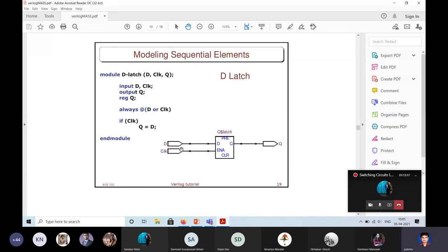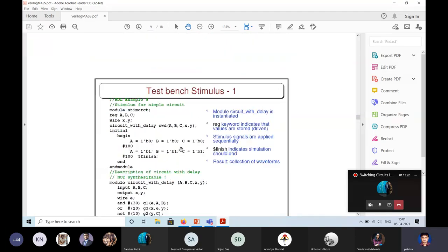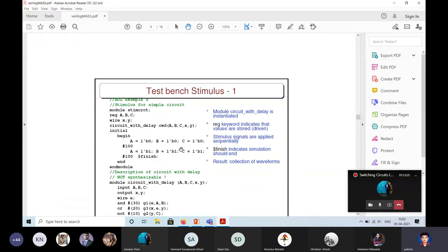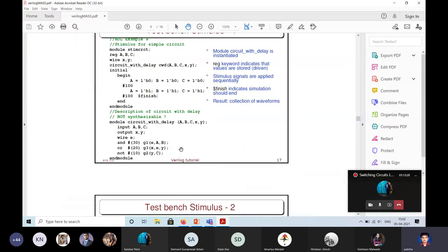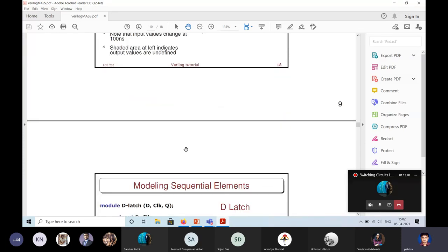This is a D value. By the way, you can initiate these wire variables. They can be of different types. These wire variables can be supply 1, a logic input of 1, supply 1, supply 0. There can be various types of wire variables, which are like constants.